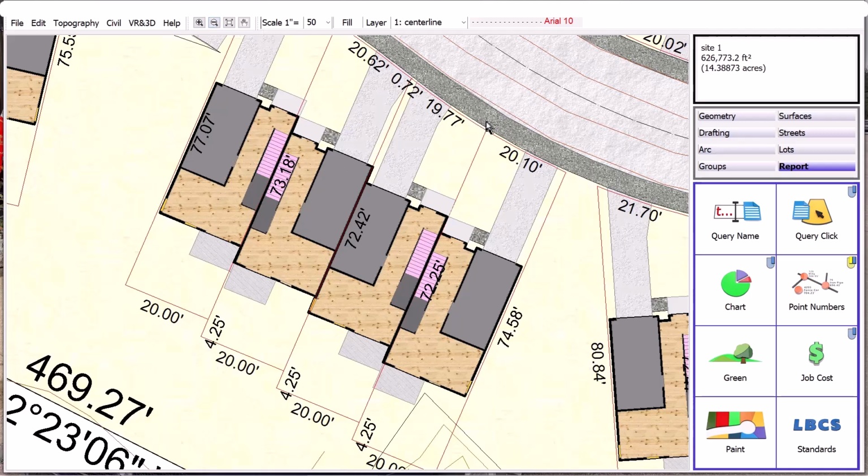The walk itself and the pavement width is the same, except I'm using a 20-foot minimum from the edge of the walk. I believe that the previous plan would have cars overlapping the walk, which would render those walks pretty useless. I did add a front porch on the units, and so we broke down all the geometry.